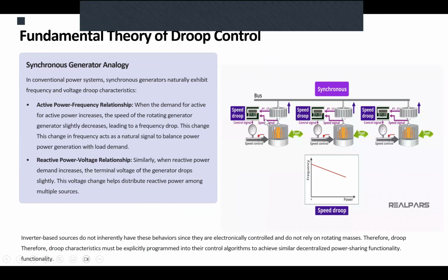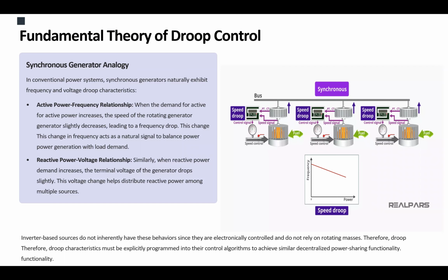Now, as we said, the idea of the droop control comes from the speed control in a rotary machine. In a rotary machine, if you have an increase of mechanical load with respect to injected electrical power, the speed would go down. It's overloaded. So the speed controller in the rotary machine would try to catch up by injecting more electrical power, so it would compensate the speed and keep the speed at a certain level.